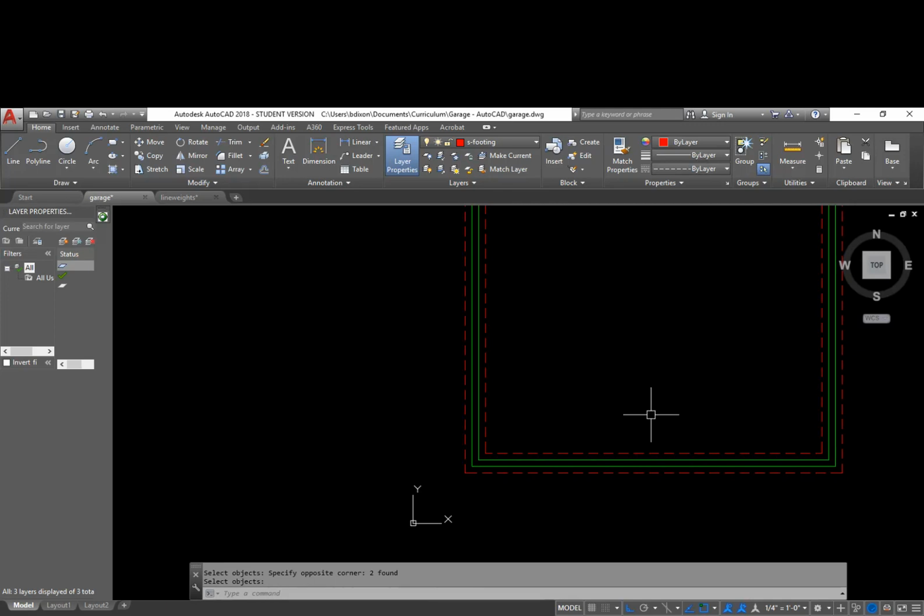So the rule is, if we have an even number of feet, the inches must end in 0 or 8 inches, and if we have an odd number of feet, the inches have to end in 4 inches. And we do that basically so that we don't have to cut any block.